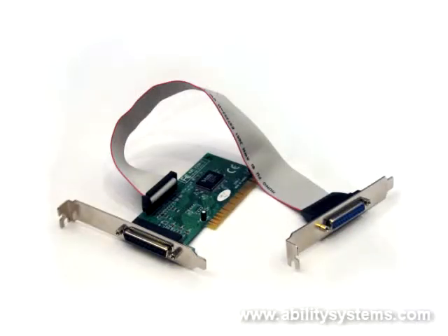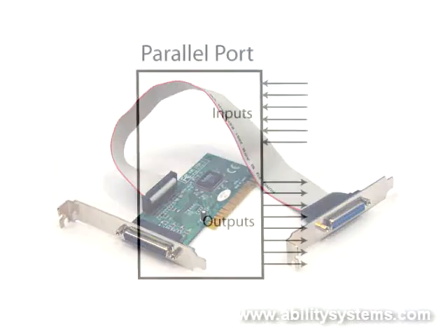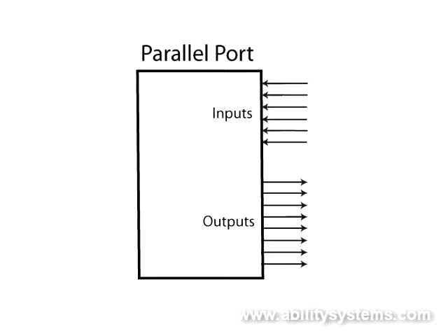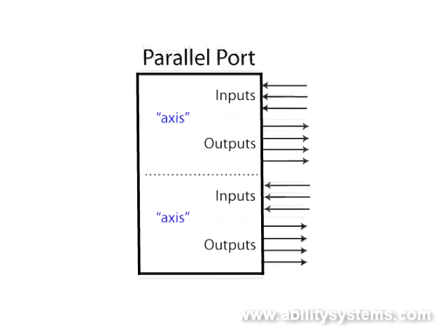with control signals. Signals manipulated by the software generated from the computer are called outputs. Signals from sources outside the computer that are sensed by the software are called inputs. Indexer LPT software supports 8 outputs and 6 inputs on each parallel port connector. Indexer LPT references these signals in 2 electrically identical sets, so each set consists of 4 outputs and 3 inputs.